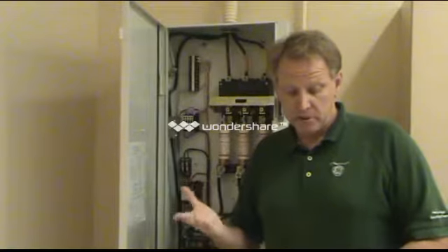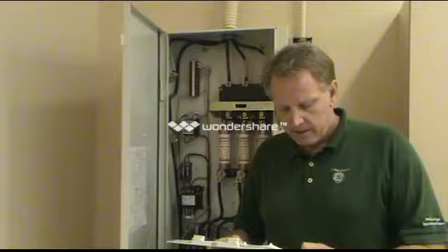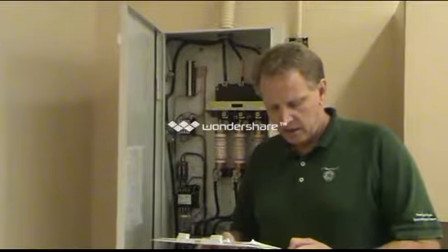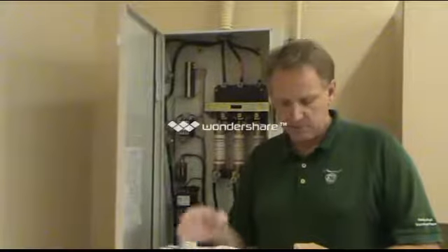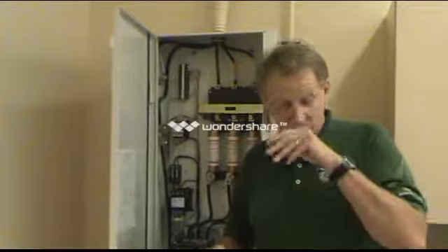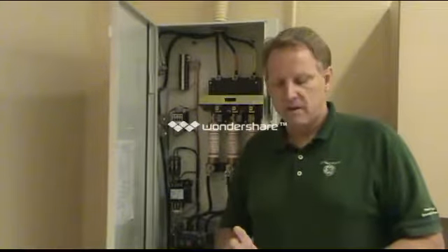It could be your shunt trip device, but it doesn't have to be the shunt trip. All right, verify your e-stop shutdown devices are connected and properly functioning. This is something you guys should be typically doing on your PMs and your installs, so I trust you'll have that done.